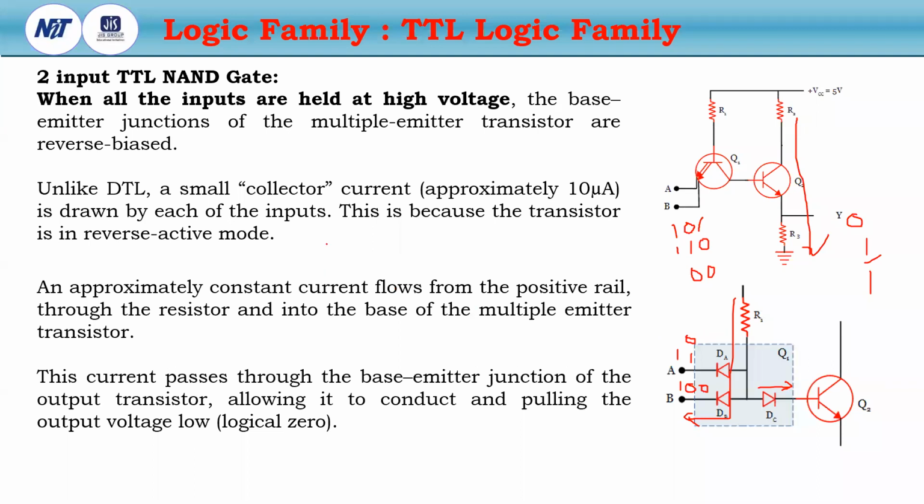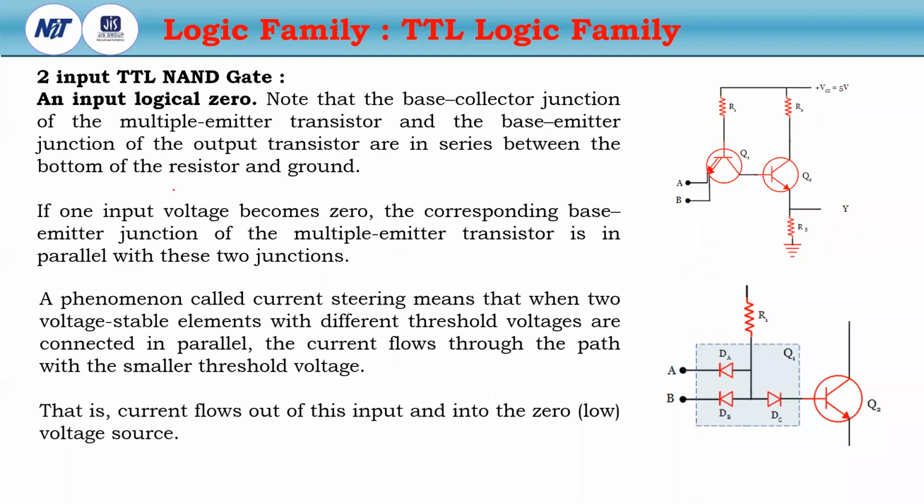So now, here I also described an input of logic 0. Note that the base-collector junction of the multiple emitter transistor and the base-emitter junction of the output transistor are in series between the bottom of the transistors and the ground.